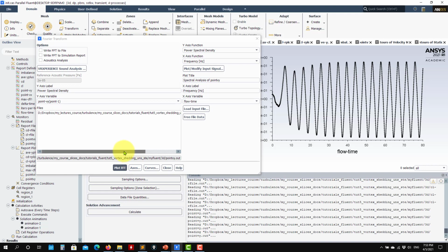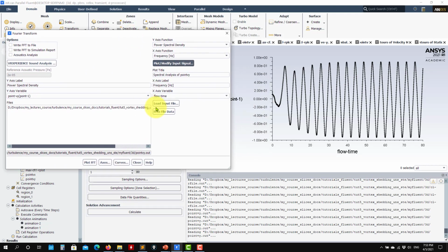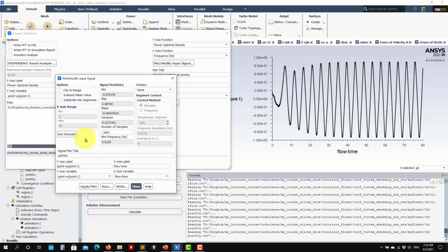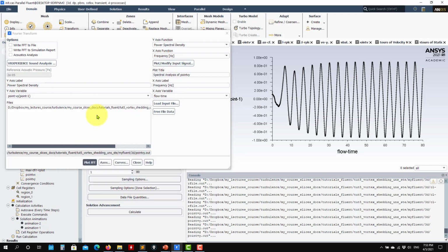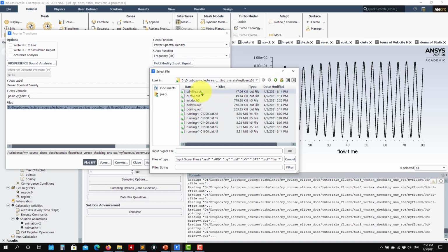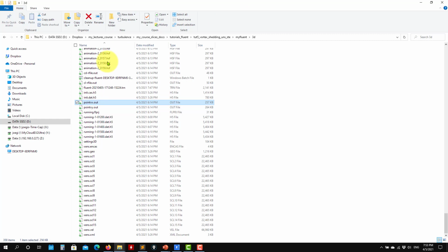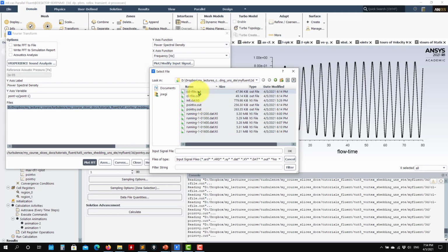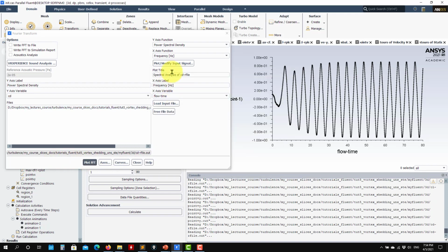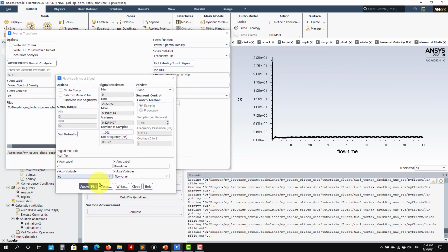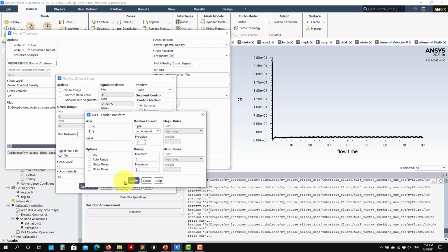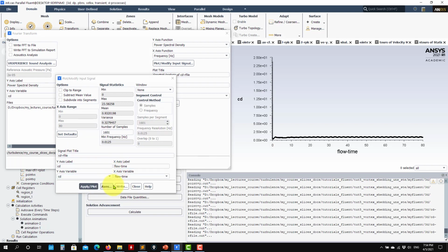Okay, so let's say for instance now that I want to find the dominant frequency of a particular file. So let me load another file. Usually, remember, all these files are saved in the directory where you are running Fluent standalone. If you decide to run from Workbench, look in the files, because everything is hidden in your data structure. But okay, let me open, let's say, CD. I go here, plot, you have that signal. Let me adjust the axis.